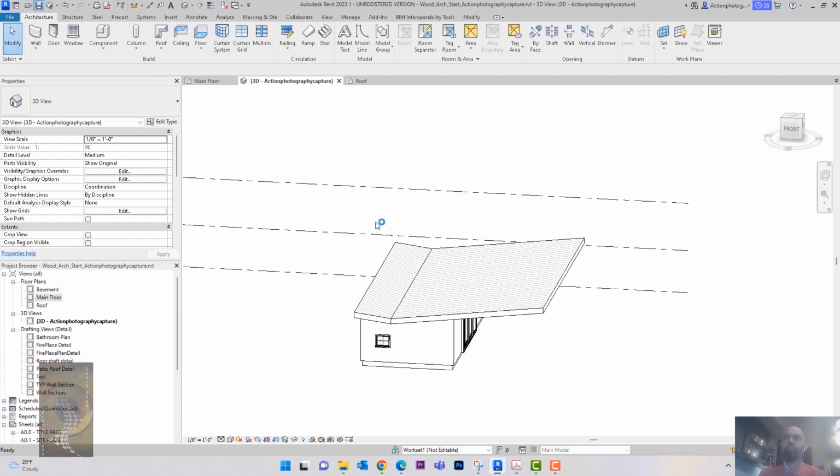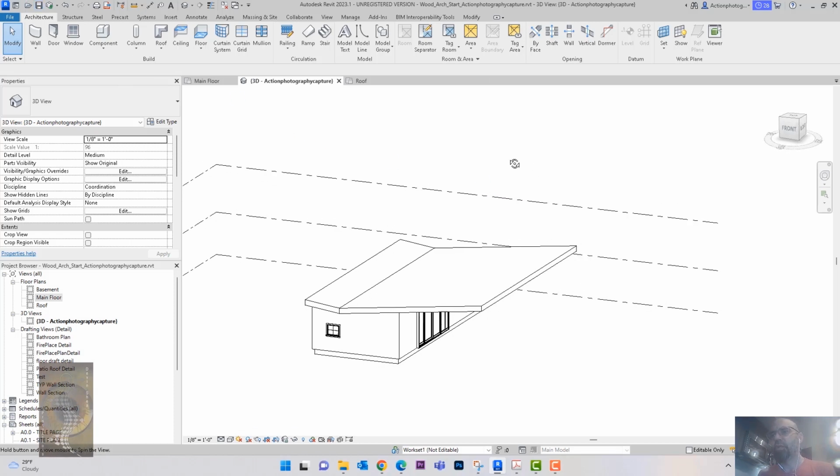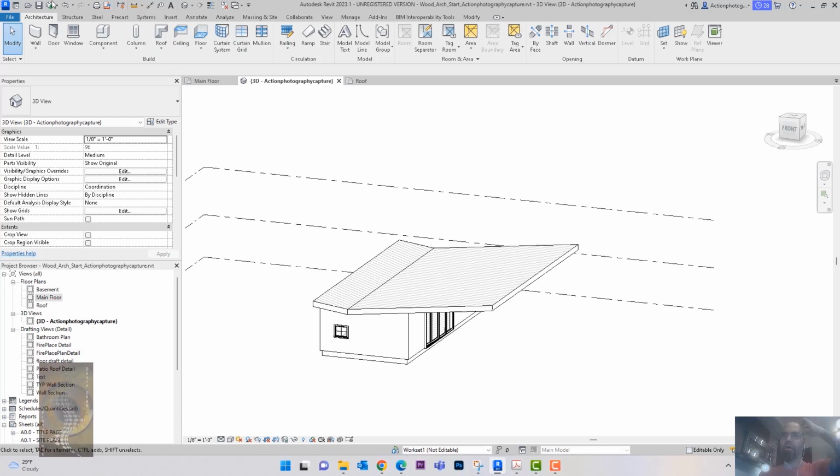This file will be a central model, by the way, because we need it to do many other things. So if using a central model and you are new, what you have to do is press the synchronize button to save it, which saves everything.